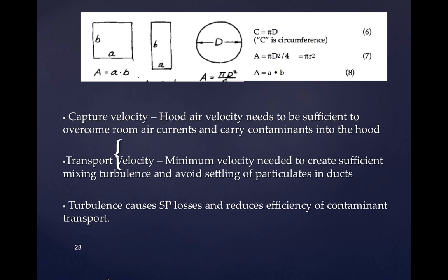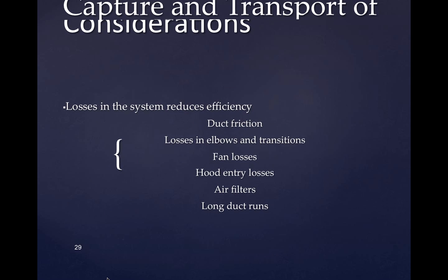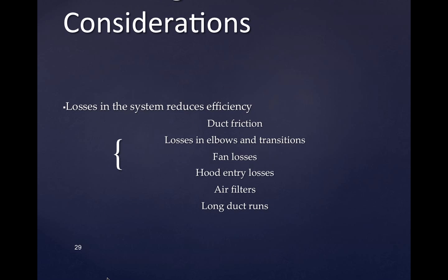What if the ductwork never changes cross-sectional area? All through the exhaust system, it's always 12-inch diameter ductwork through the entire system. What's the velocity throughout the entire system? It's always the same also, because you're not changing the area, so the velocity is always the same. Most exhaust systems, once you start sending this through ductwork, you're probably not going to see much in the way of transitions unless you have a reason to have a transition, like entering a filter or leaving a filter or something like that, a different size ductwork that you need.